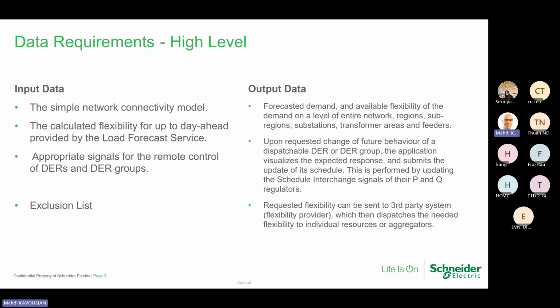And similar to what we explained this morning, it can support an exclusion list. Also, if you have load flow, it can do calculations and look after the load flow. It doesn't send any command that impacts your own network. This command was sent by the transmission company, but you also don't want to overload your own limit.